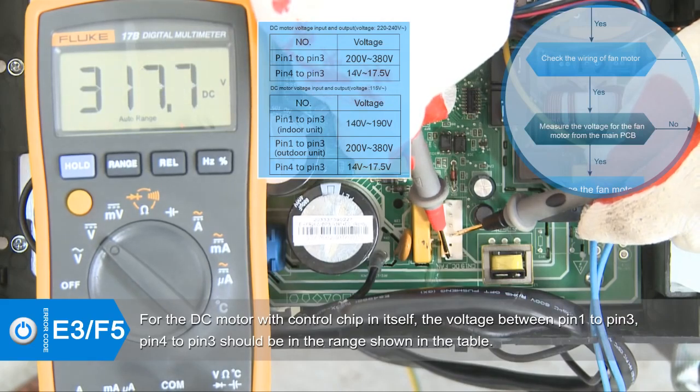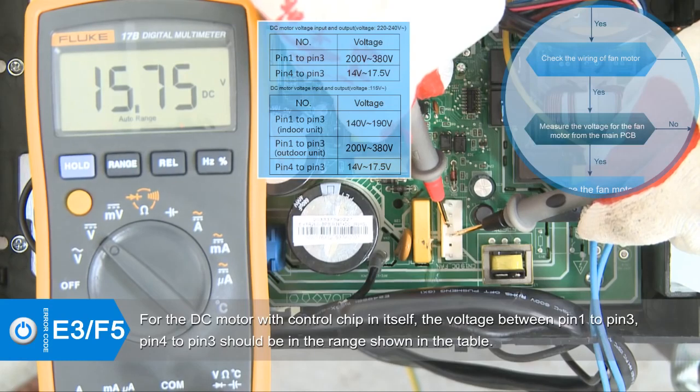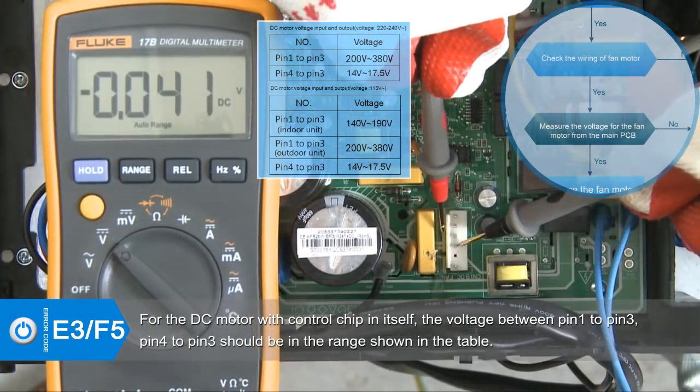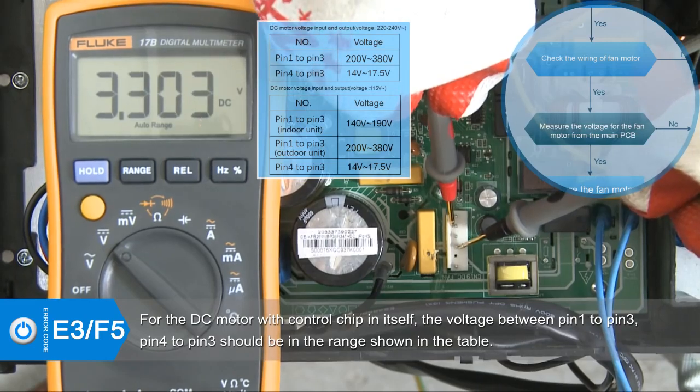Examination for main PCB board. DC motor with control chip in itself. Turn the power on. When the unit is in standby mode, measure the voltage between pin 1 to pin 3, and pin 4 to pin 3 in the fan motor connector. If the value of the voltage is not within the range shown in the table.